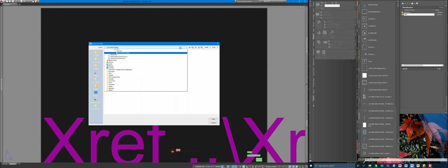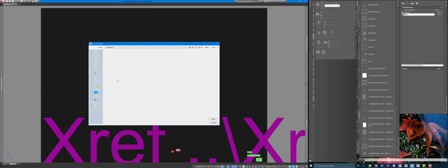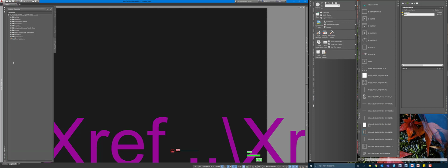Now, you can also, down here in model views, and this is rather nice, add the location for your project in the Windows browser. So this is also usually something that I do. So instead of trying to find files in the Windows Explorer, I can just open my AutoCAD for the day, pull up this sheet set, and I can dip into particular files. For example, I can dip into the base and work with the X references, as opposed to going through the sheets to get down to that X reference. You can just have your file location right there as well, ready to go.